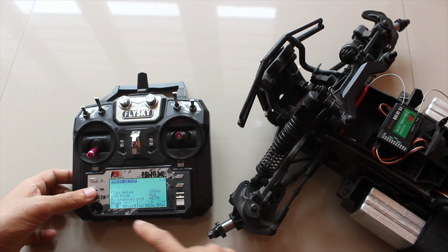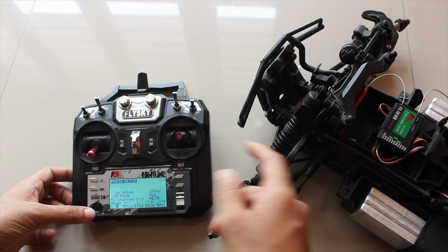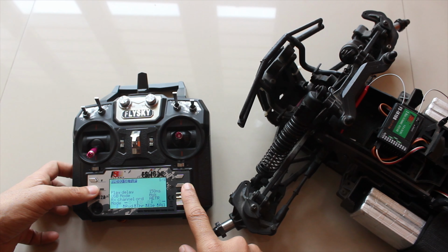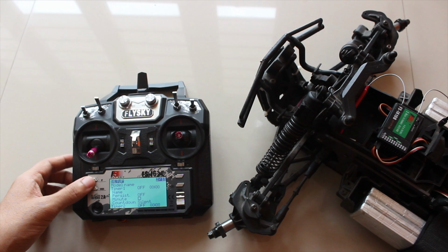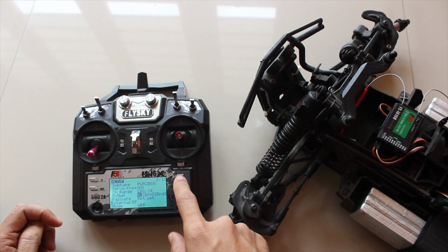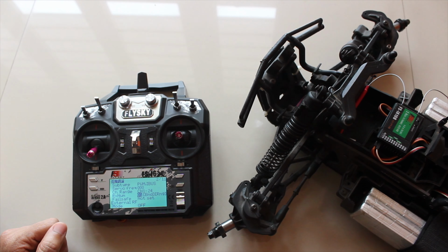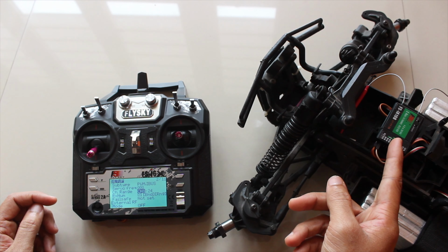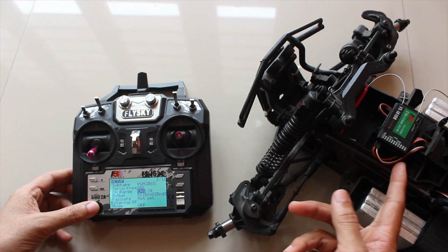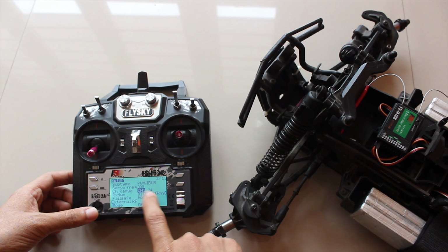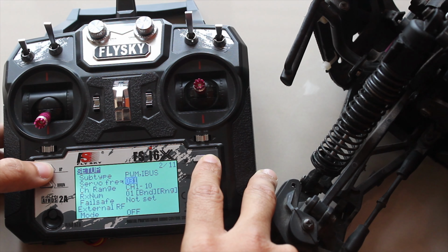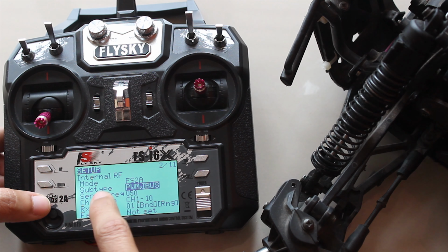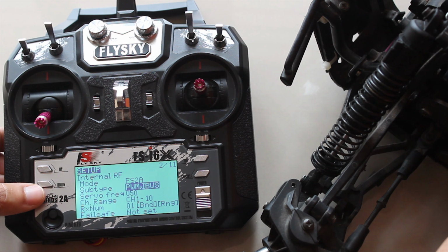In the radio setup, I'll make sure that the mode is set to what I want. For RC car, I use mode 4, so I'll set that to number 4. Then I'll go back to the model settings and set the receiver number to 1. The previous receiver in my FPV quad was assigned to number 0. This particular receiver only supports up to 10 channels, and I'll be using PPM or PWM, so I'll set the maximum channel number to 10. The servo frequency is set to 0, so I'll set that to 50, which is default. And I'll leave the subtype as PWM because the ESC in my RC car supports PWM.